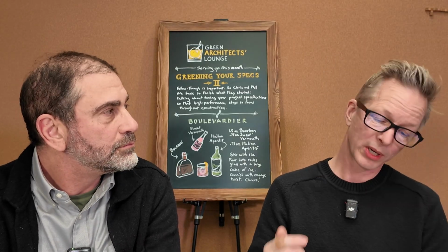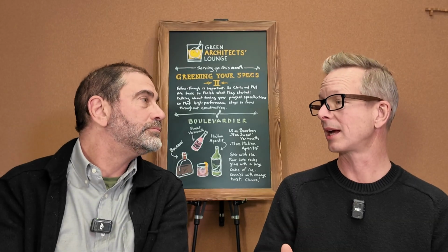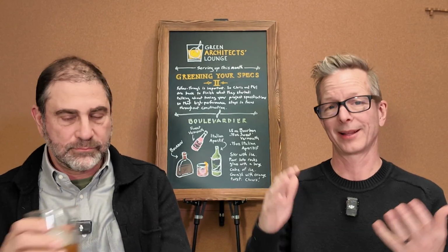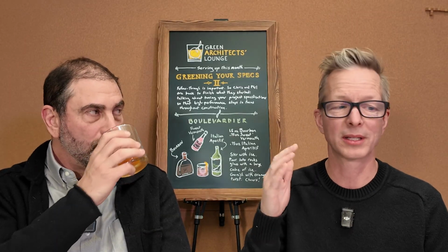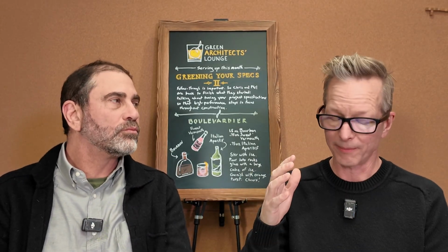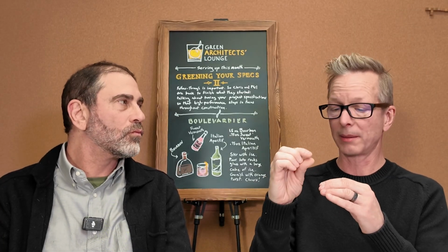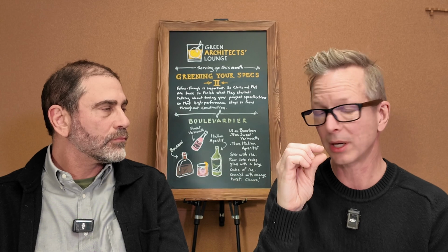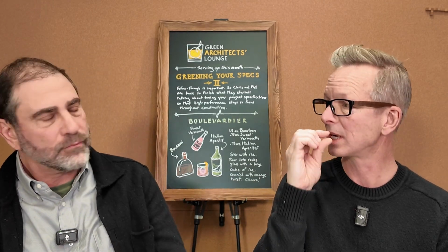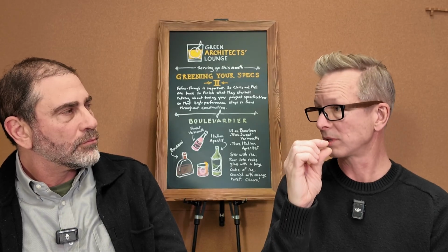And that brings us to the alternative, maybe if it's going on a slab: an engineered floor. We're just going through products right now, but these are things you can think about in your specs. It's basically like plywood, tongue and groove, but the top 1/8 of an inch, or 1/16 of an inch, is an actual hardwood veneer that you can sand once or twice.